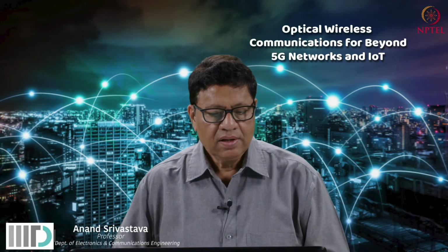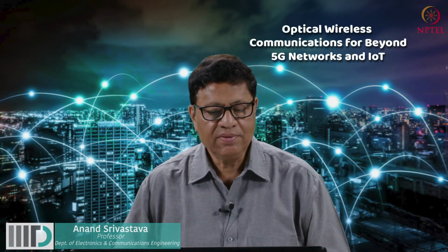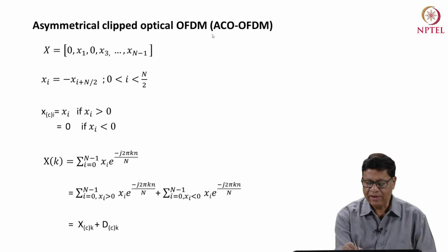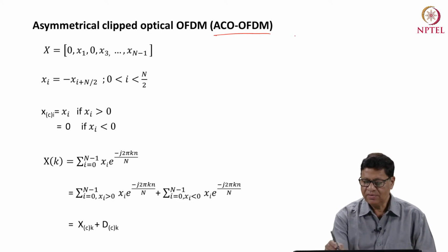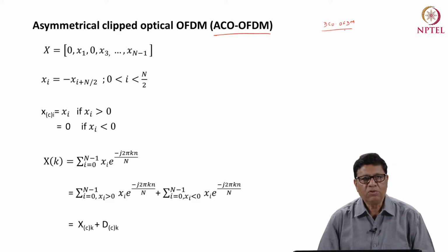Hello everyone. So today we are going to discuss another modulation technique, which is asymmetrical clipped optical OFDM, also called ACO-OFDM. In the last class, we had discussed DCO OFDM, where in order to make it unipolar and real, we had invoked Hermitian symmetry, and also we had given a DC shift.